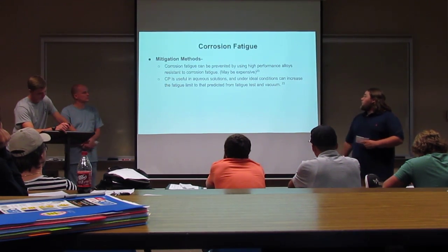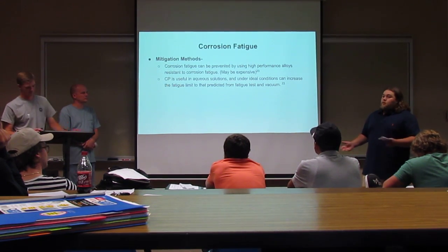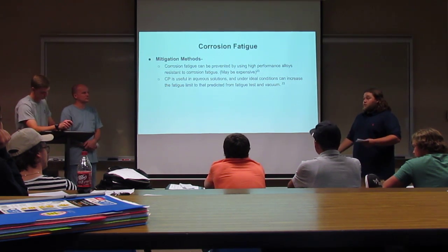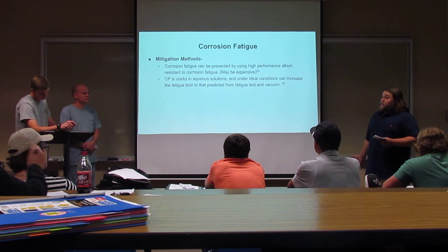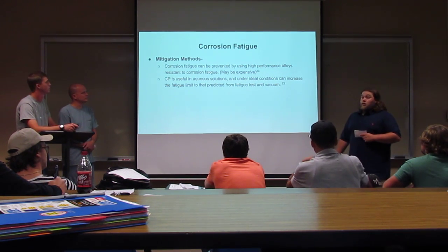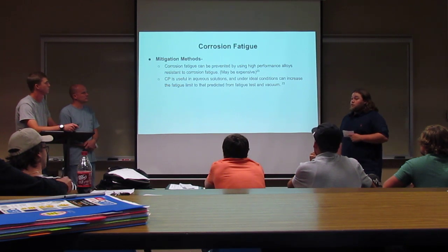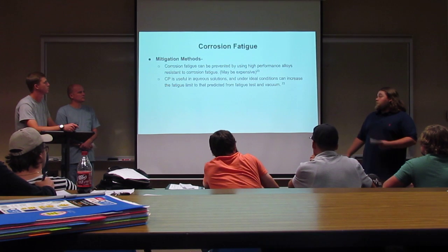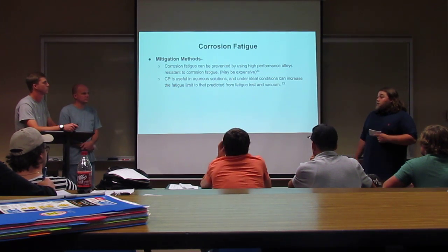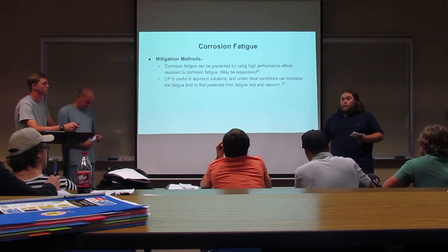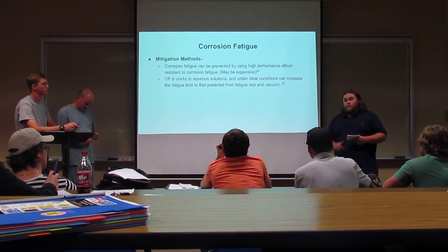Mitigation methods. It can be prevented by using high-performance alloys that are resistive to corrosion. They're a little more expensive. CP systems are useful in aqueous solutions, and under ideal conditions, using CP can increase the fatigue limit. It means it'll hold more load stress and cycle stress.